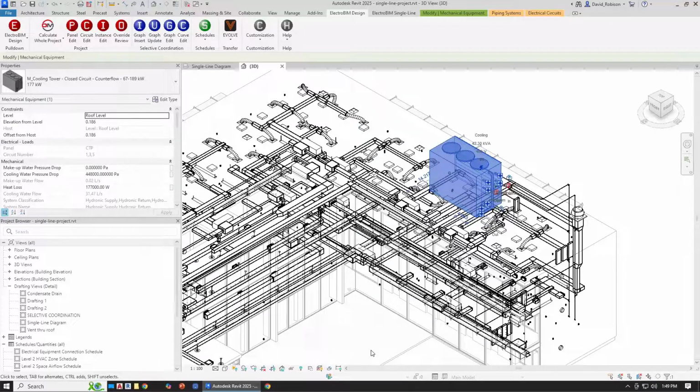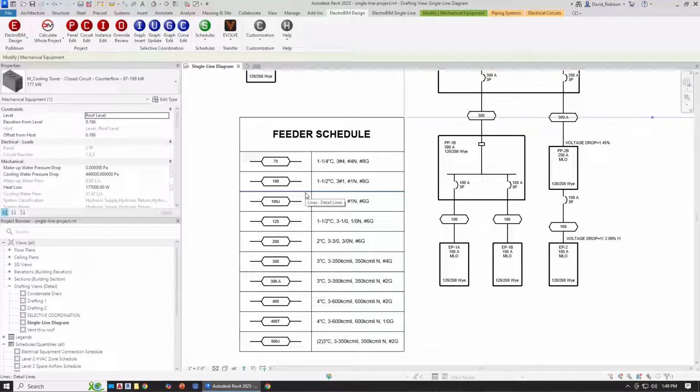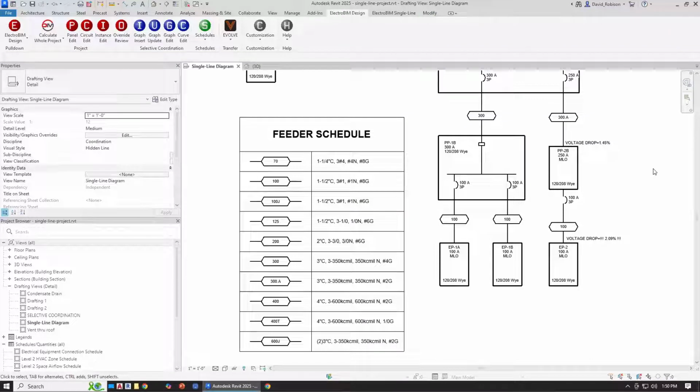There is also NEC 250.66. It used to be that 250.102 referred back to 250.66 for the sizing. Somewhere around 2010, they split those out. So it's been 15 years now, but they actually split those two tables out. They're the same table, but they have the tables in the two separate places to make it a little more clear. So that's, again, they've been slowly massaging this ground section to make it more clear.